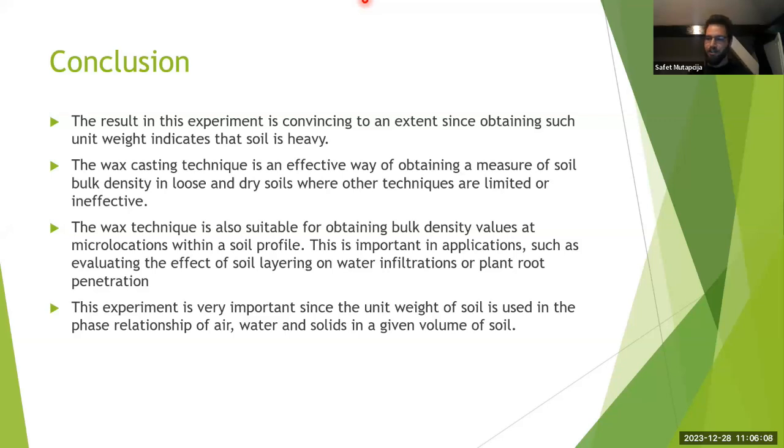So it's basically fake cohesion. Because of the water, the pores can hold soil particles together. So when you put just a little bit of water in your sand, the effective cohesion is going to act like cohesion, so you can build whatever you want. Same with compaction. Depending on how much water you have in your soil, if you have the right amount, it's going to be super easy to compact. With any method you can use, even just walking over it, it's going to compact.